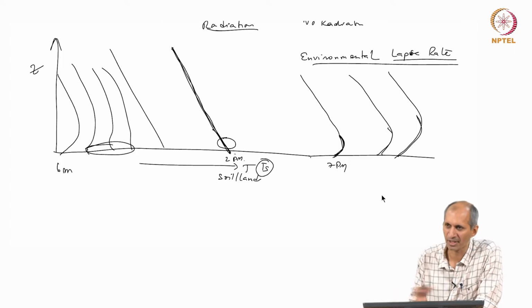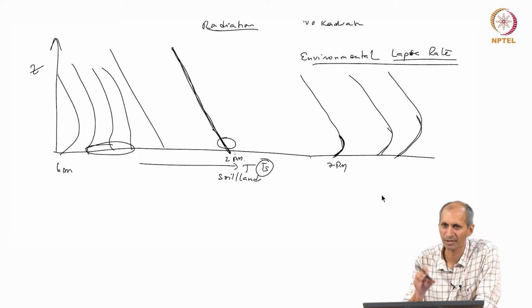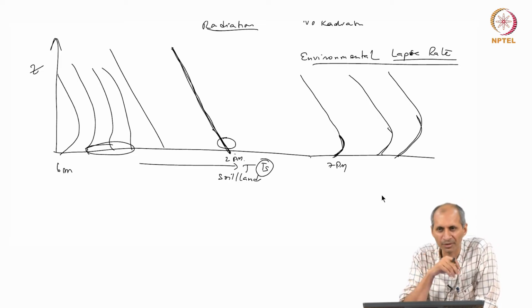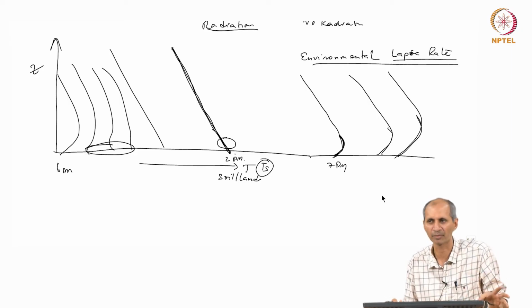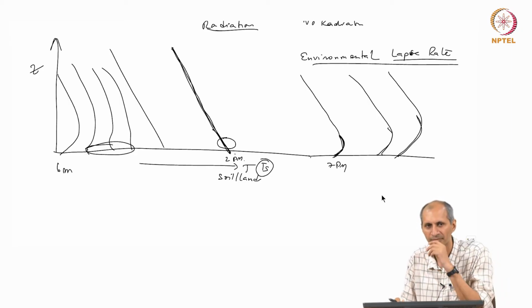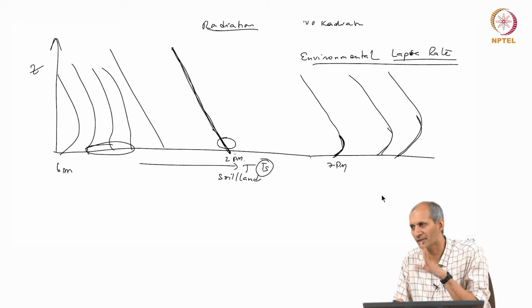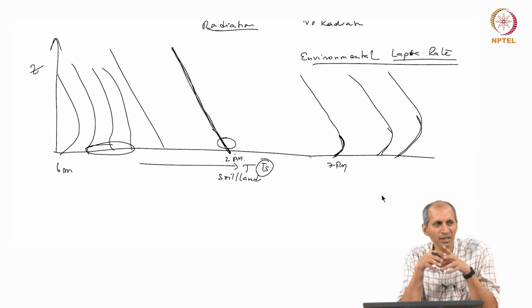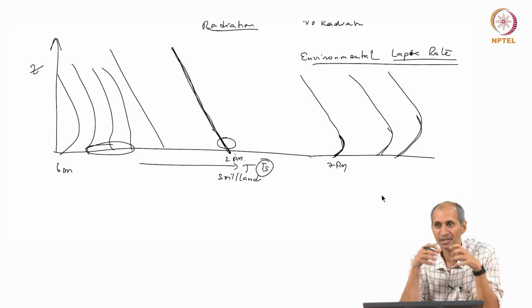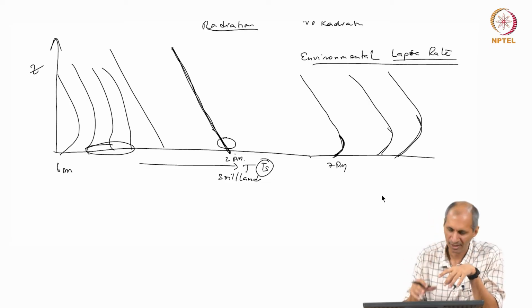In this system, this is how the environment looks in terms of temperature. If I drop a parcel of air coming from a pollutant source, for example, if I am running a diesel generator in the middle of a field, what will happen? It is generating some gas at some temperature and you want to see what will happen to these air parcels. I am taking the case of an engine because it releases parcels of air at given intervals, let us say a puff of air, so we can see what happens to it.